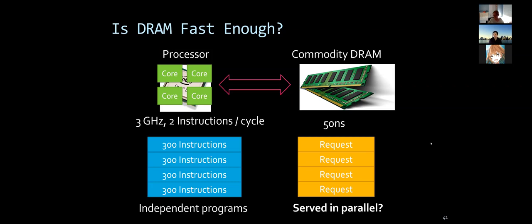How do they argue that it's 7 nanometers? Around 10 to 15 years ago, Dennard scaling, which is not covered in this course, but it is a scaling mechanism that drove this industry for 40 years, stopped because of power issues. They needed to survive somehow. So they started to use naming conventions where, when you use a new material, it looks as if you scaled from 10 to 7 and reached the same performance, so they use the same name. They make their circuit faster, but it's not necessarily smaller.